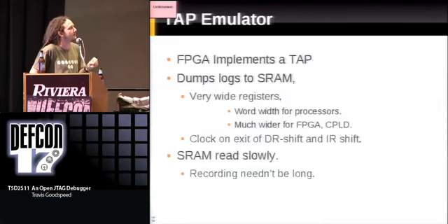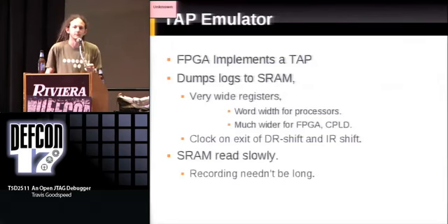And it's also possible to build a TAP emulator. If you had, say, 10 chips, or let's say 2 chips, of the same model, and you wanted to program them at the same time, you could just connect them in parallel, but leave one of the TDO pins disconnected. Then you could send whatever traffic you liked into the chip, the commands to read and write flash memory, and while you will only hear responses from one of those chips, both chips will be written.